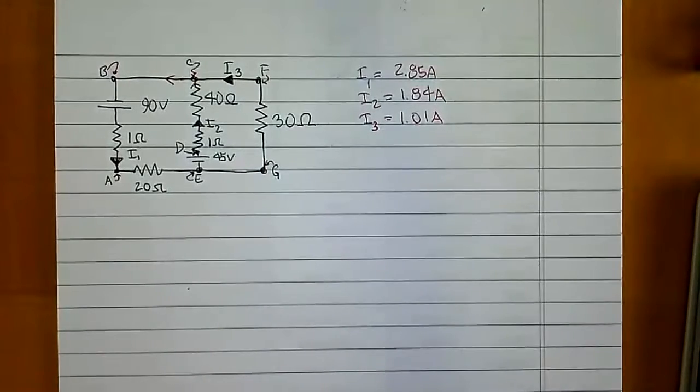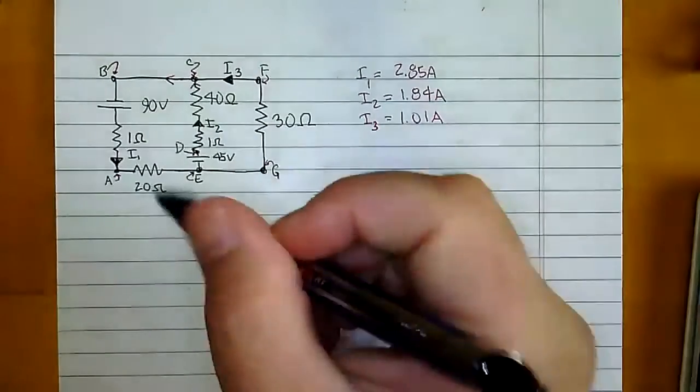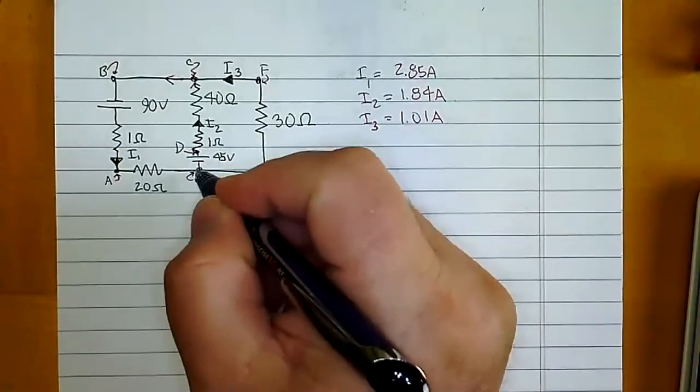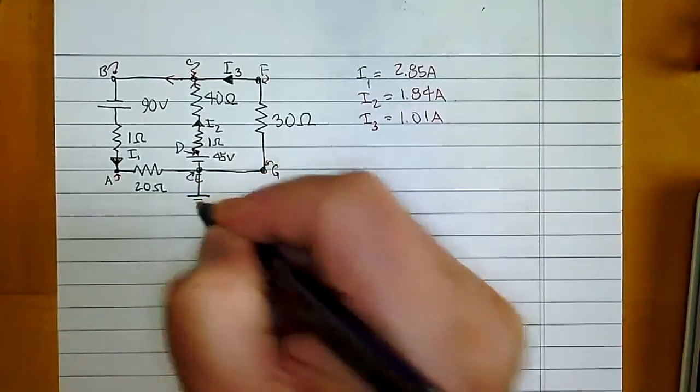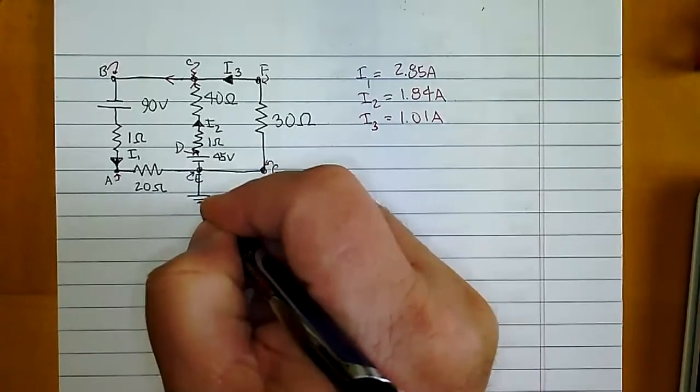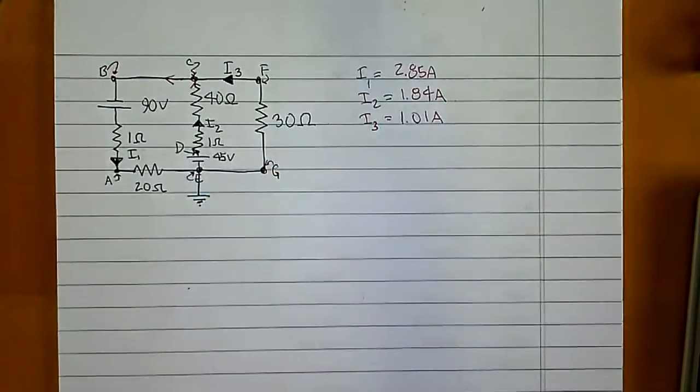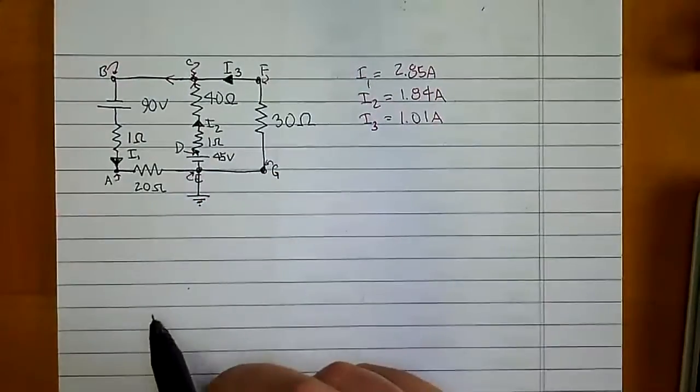Now the problem with this is it actually introduces a fourth variable in this particular circuit, one additional variable, but it does so in such a way that the algebra that has to be done makes life a lot simpler. So what we do with the nodal method is we, one, arbitrarily call some point the ground. This is just like in potential energy where you were allowed to assume the potential energy was zero anywhere you wanted. And as long as you stuck to that, the problem worked out. So I'm going to put the ground right there.